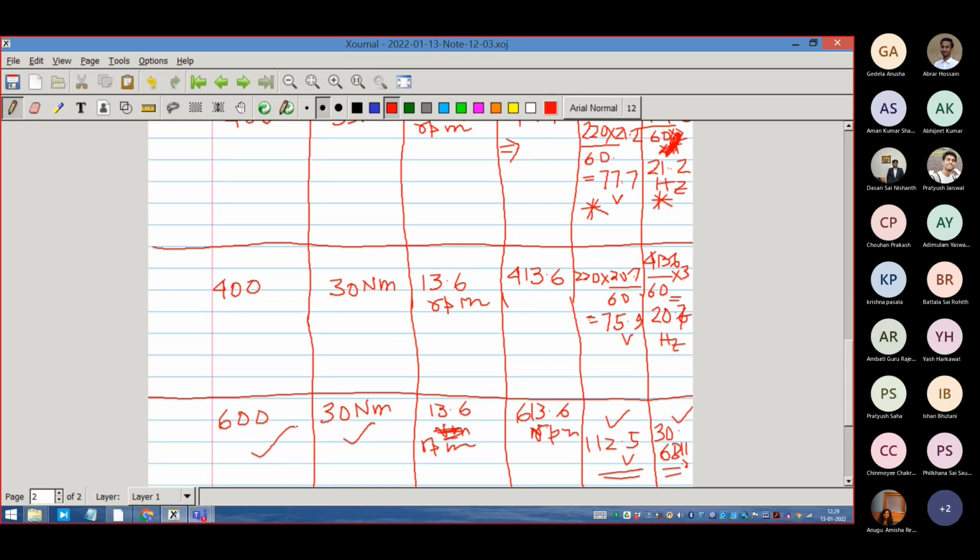Okay, this is the way the equilibrium will be established, because the machine will be developing the same torque as the load torque. So there is no further acceleration or deceleration. Till it happens, the machine will be either accelerating or decelerating, and there will be a search for the right amount of S omega s. This S omega s has to be searched by a closed loop control system. That is what will be the method involved.